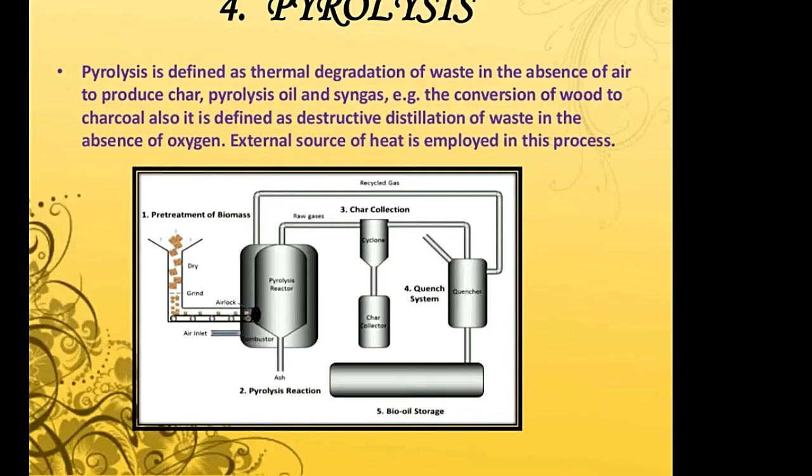The pyrolysis, somewhat new. Okay guys, this is some kind of new technology in reducing waste. Pyrolysis is defined as thermal degradation of waste in the absence of air to produce char, pyrolysis oil, and syngas. Example, the conversion of wood to charcoal. Also, it is defined as destructive distillation of waste in the absence of oxygen. External source of heat is employed in this process.